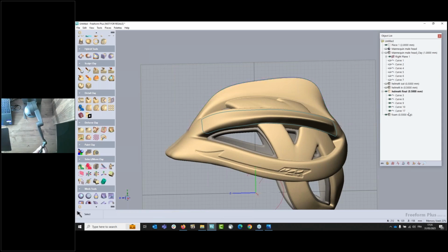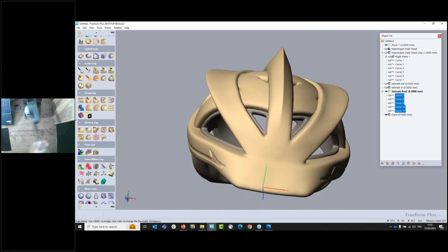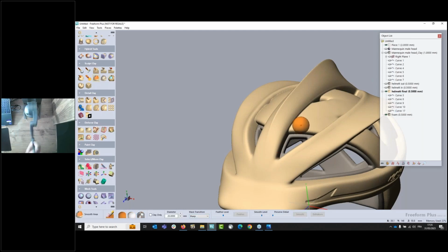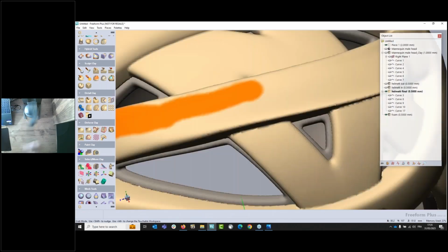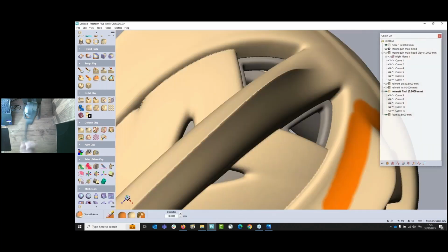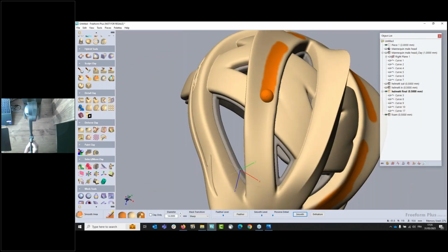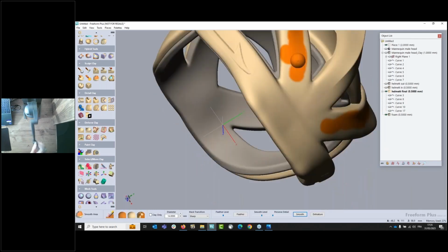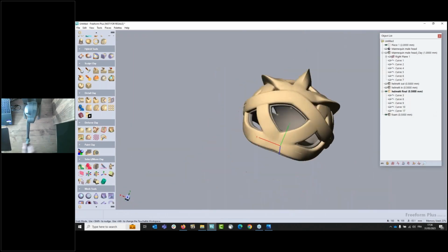I can hide all my curves. It's looking more, not aggressive, but yeah, sporty. Let me now smooth the small limits I have here just by painting this. And the same here on the other side, just paint that. I can make it manually, but this is easier and faster. Paint it like that. I accidentally selected this edge. If I press Ctrl, I will activate the eraser to remove the selected area. I will choose the smooth level, then smooth. Here it is. It's almost finished.